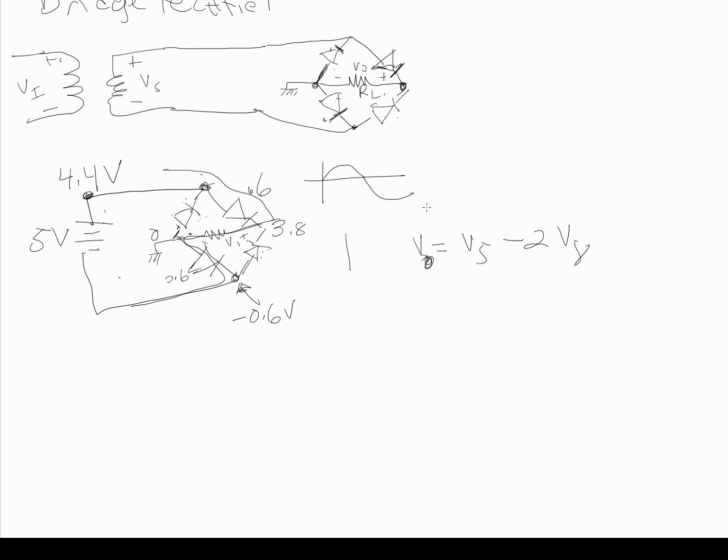So your maximum voltage out is going to be a little bit less than the center tap one, because on the center tap one, each cycle V out is going to be equal to Vs minus V gamma. This is for the center tap, and this is for the bridge, because each cycle it drops over 2 diodes.